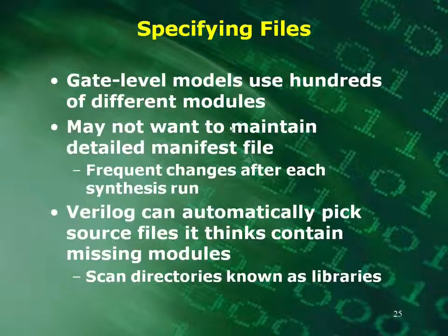Okay, gate level models use hundreds of different modules, and you may not want to maintain detailed manifest files with frequent changes after each synthesis is run. Verilog can automatically pick source files that contain missing modules, and we can scan directories known as libraries. So let's take a look at how you can do this.